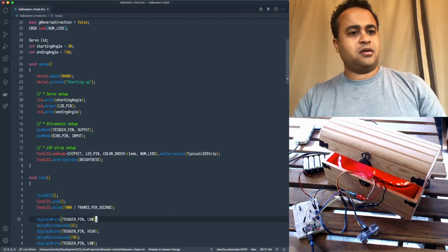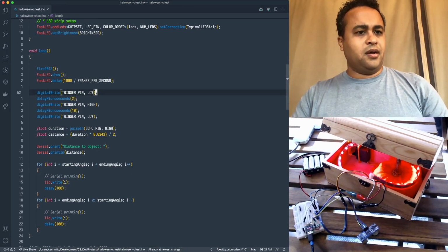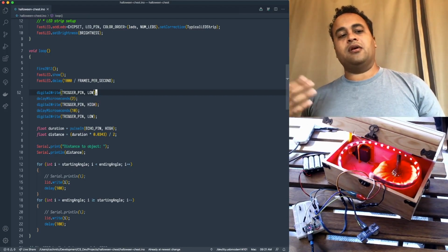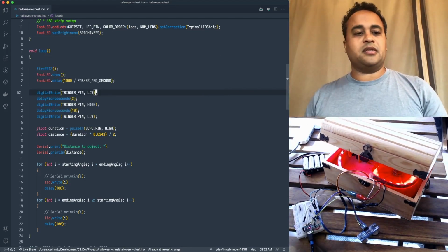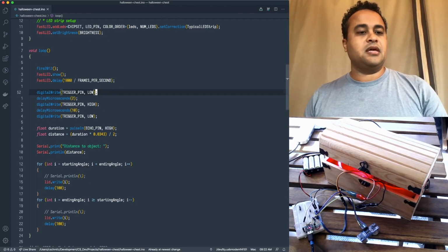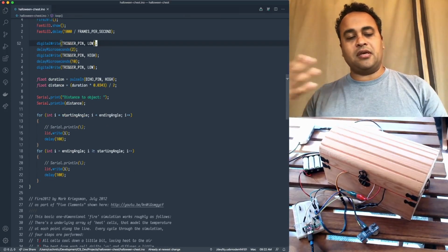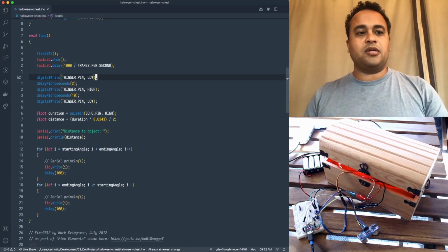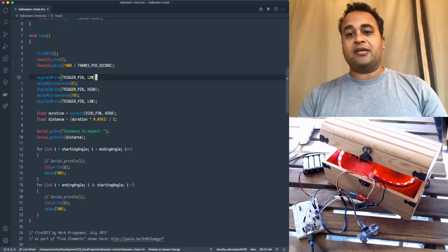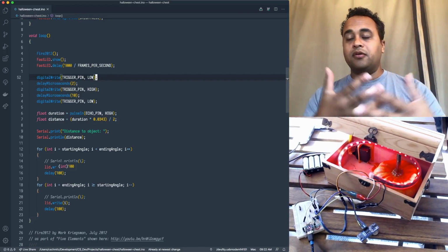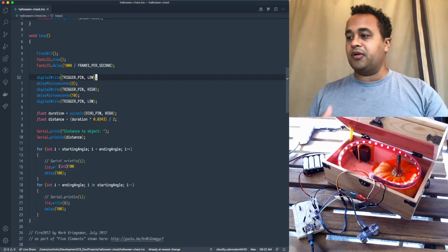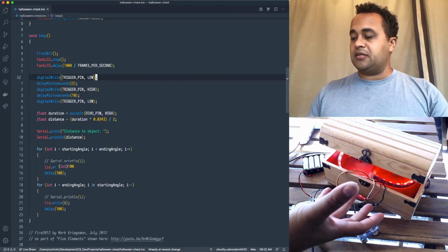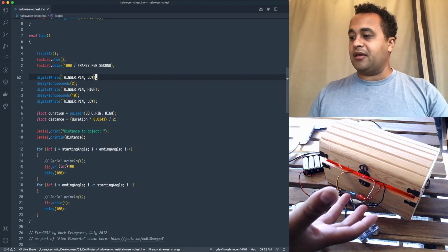If we look at the code down in the loop, we have the light pattern firing. We have the ultrasonic sensor doing its measurements and then calculating the distance, and then we have the servo motor lifting and closing the lid. But because all of this is written using delays, we're actually stopping the microcontroller multiple times before it can move forward. And specifically with the servos, this delay is slowing everything down.